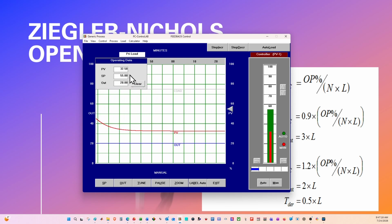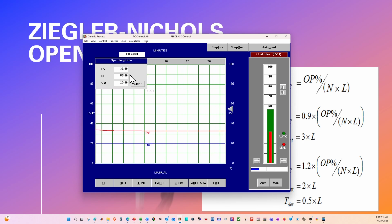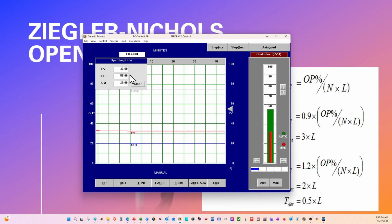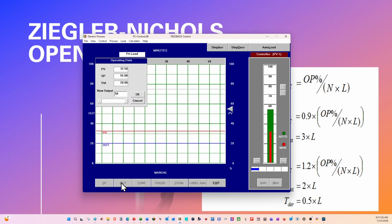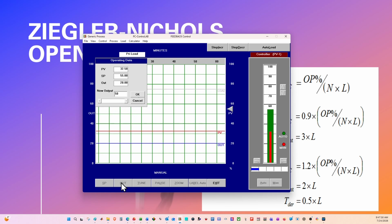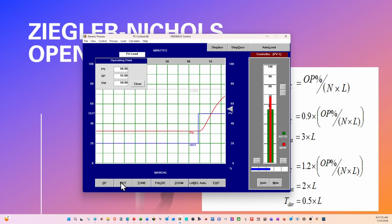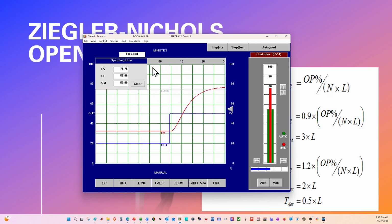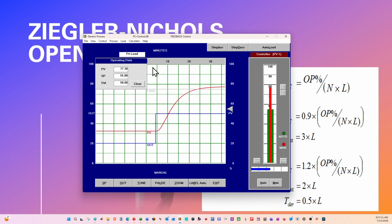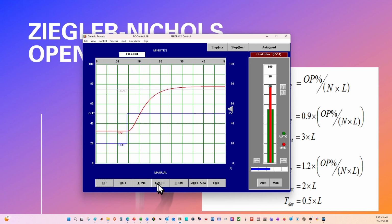Now I give it a step change, and you can change it as much as you want to. I always recommend that you change it just enough, more or less, in the place where you are doing the control. So I'm going to change my output to 50%, and let's have a look at what it is going to do on the process. So with an output of 50%, you can see that my process variable is probably going to go up to about 77.5. Great, that's it. So I'm going to pause the screen.